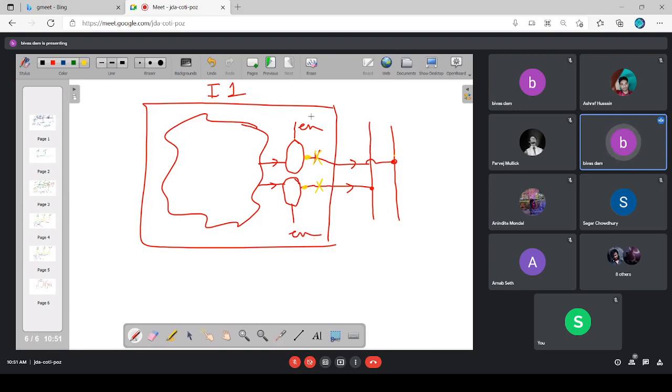So that electrical signal will actually get transferred to the data bus wires, individual wires. But that will happen for only one particular input device, because by placing the proper address, I am ensuring that only one input device gets enabled. The other input devices are remaining in disabled condition. So there, the final stage outputs will be electrically isolated, whereas only one input device will make sure that its output is electrically one viable data, and it will place that data onto the data bus. Now tell me what is the problem.